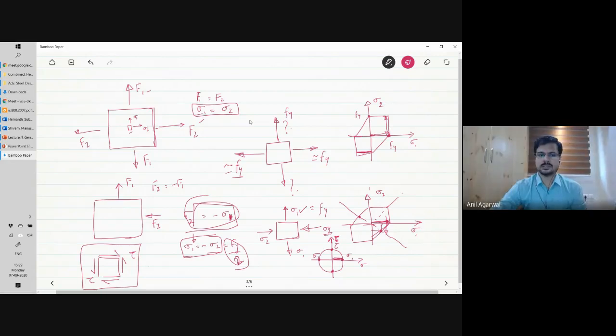It is legible. So in that Mohr circle, you have this state, and in this particular orientation, you are here and here. These are the two 90-degree planes, tau and minus tau. One of them is tau, the other is minus tau, or you can call them whichever you want. Then the corresponding principal stresses will be sigma 1 and sigma 2, and they will also be equal to tau.